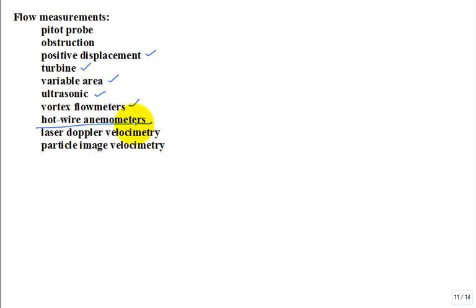Let me just quickly explain hot wire anemometer. You have a wire with known resistance, and you pass a current through it, and with that current through it, you will dissipate some heat and it'll get hot. But if you have fluid flow, like airflow, over it, guess what? It cools it down. And the resistance of that wire is well calibrated as a function of temperature. So you measure the voltage across for a given current, and you infer then the resistance, and then you can infer back the temperature of the wire, hence the convective cooling, hence the airflow.